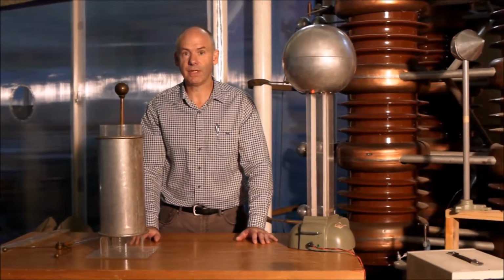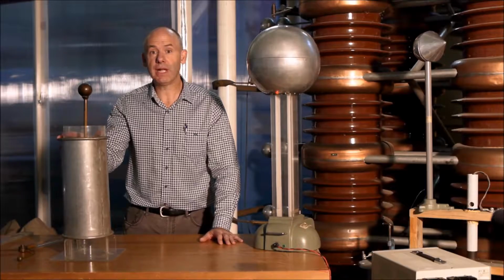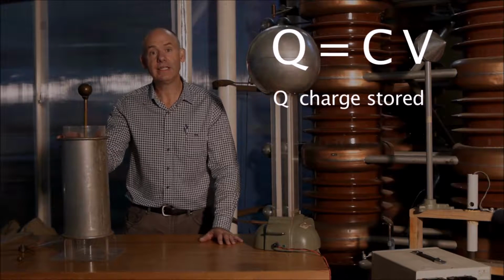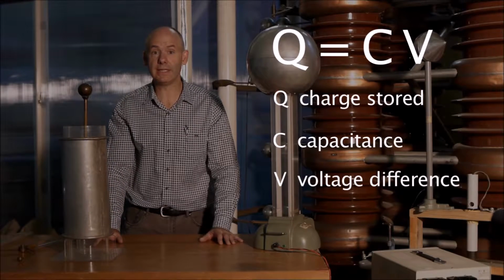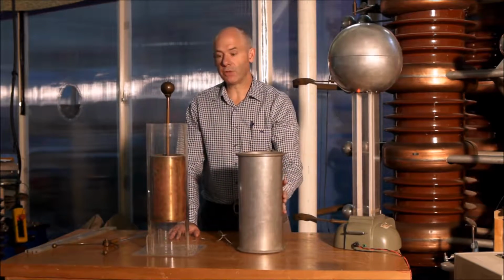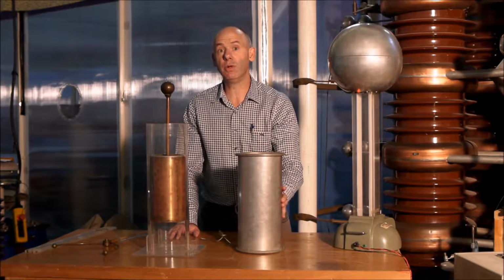The most important properties of a capacitor are its capacitance and its maximum voltage rating. As you add more charge to the capacitor, the voltage between its plates will rise according to Q = CV, where Q is the charge stored on the capacitor, C is its capacitance, and V is the voltage difference between its plates. This is important because the insulating dielectric between the plates of the capacitor will break down if the voltage between the plates is too high.